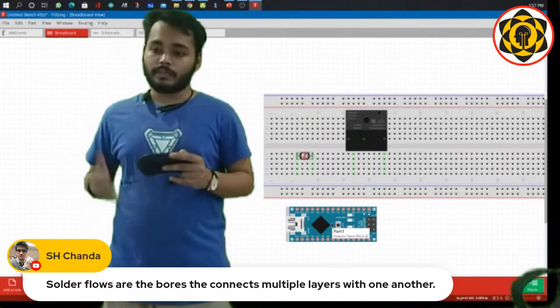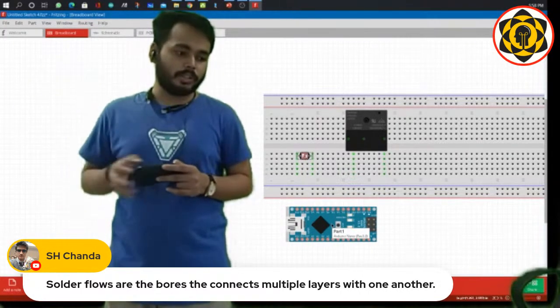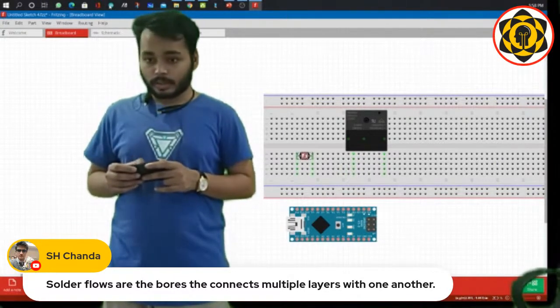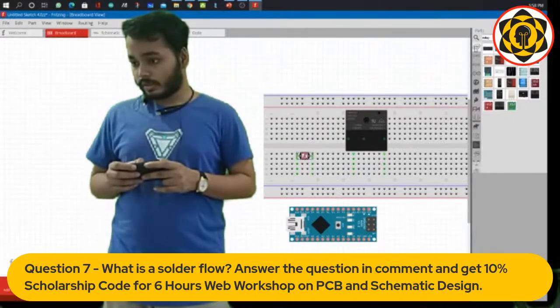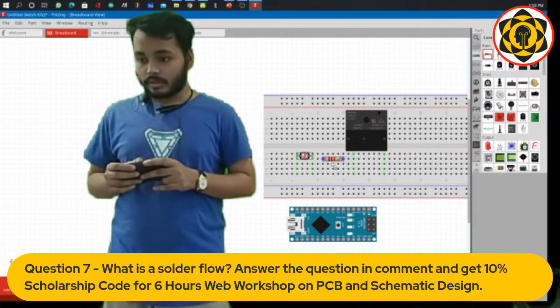Now, LDRs have two legs, right? So we need three legs for a sensor. What I'm going to do is make a voltage divider configuration. So let's get some more parts. There it is. Let me take a resistance. Let me drop it right there.